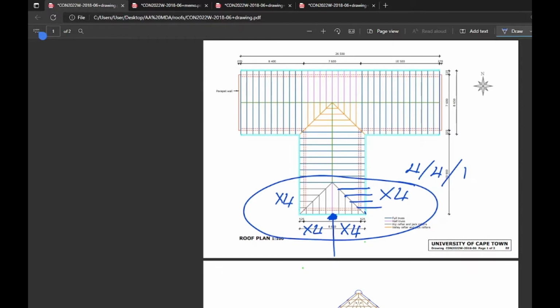And let's just take a look at other jack rafters and places where they will meet brickwork. Now remember we said that this was a full one, and this one is also a full one. So is that one. Despite it looking smaller on plan, we've considered them as full trusses. Now the other jack rafters that we've accounted for are all floating. In my mind, they do not meet brickwork. They are in the air, either suspended by our valley rafter or our soon to be ridge beam. And in this case, there is another ridge beam, right? So there's no hoop iron on that side, only here.